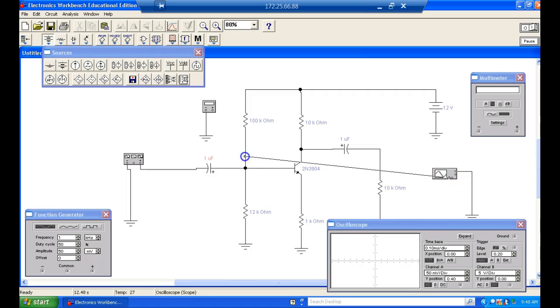Troubleshooting amplifiers, guys, is just about going to take an oscilloscope. So we got nothing here, right? Then when I go right here, we have our waveform. So we know right off the bat, nothing on this side, something on that side, then we know it's open, right? Now in real life, you'll see it'll couple through the open. So if you turn your scope down far enough, you will see something. So you're not looking for nothing. You're looking for whatever's supposed to be there, right?